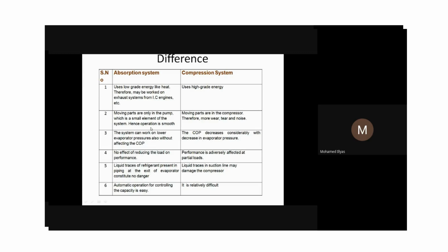So it may greatly affect the COP of the vapor compression system, depending on the pressure on the system. According to the second law of thermodynamics, heat always flows from high temperature to low temperature naturally. There is no way it is connected to that. But if you want to transfer the heat from low temperature to high temperature, we need to give work input. So that is why the COP, if you recall from the earlier, is nothing but the efficiency, the coefficient of performance of a refrigerator.